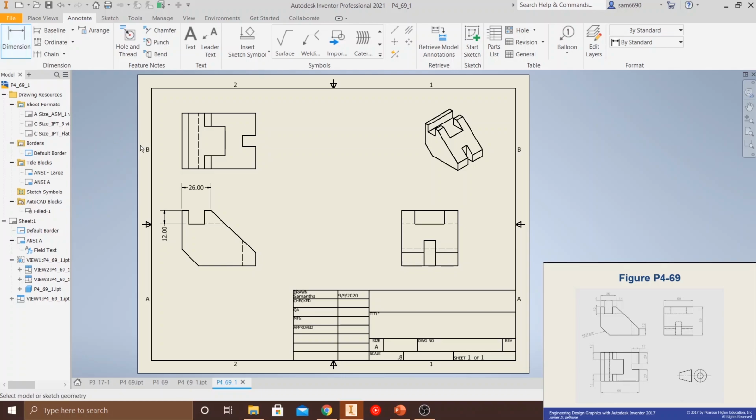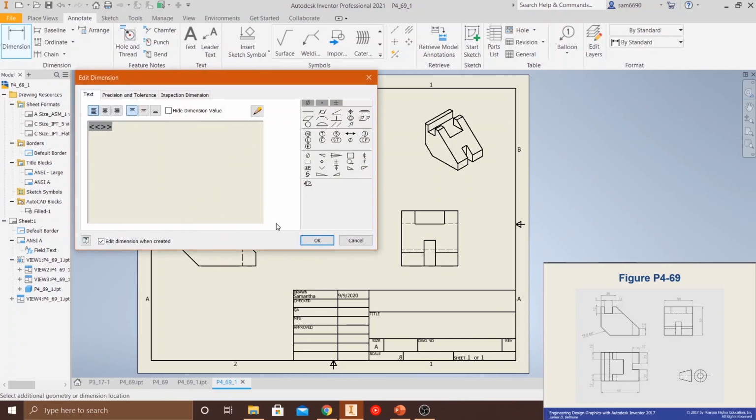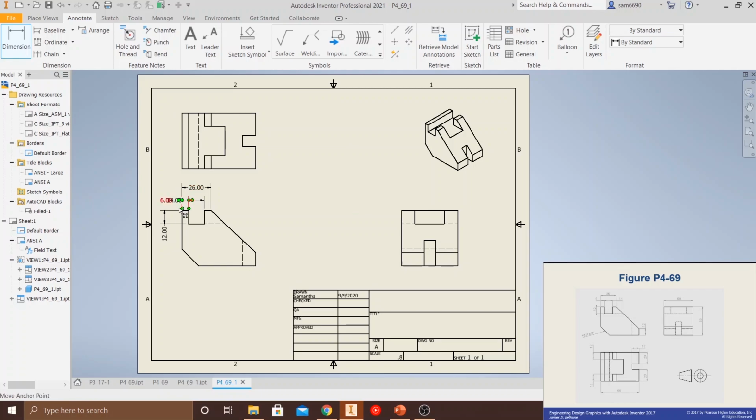Let's come to this dimension here. This is going to be 6. We're going to go right across, and put it there. This dimension here, across for 14. 14 goes across this. We're going to put it on the same line. Now again, click Escape. You should be able to switch its orientation like that. Make that a lot easier on yourself. Look how nice that looks on the same line. So easy to read. I love it.